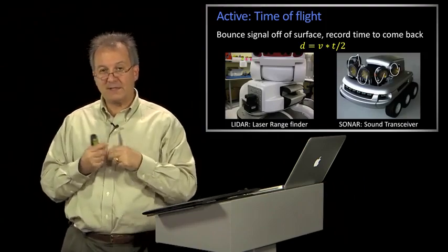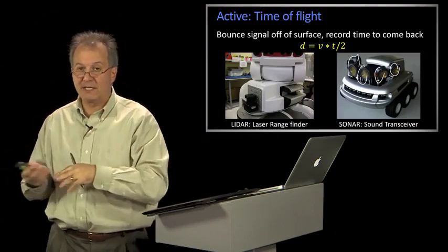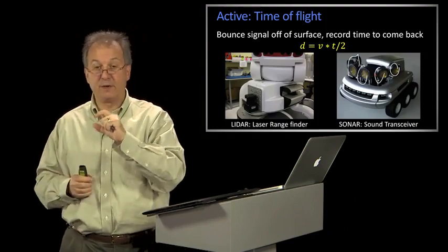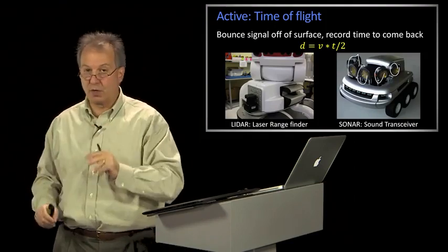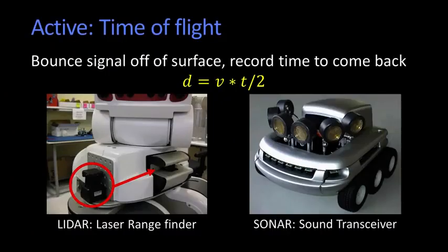One of the interesting effects of that is because they made so many of those cameras, it made those sonar things very cheap. So people started putting them all over robots and things like that and using sonar to detect depth. Much more sophisticated is what's called LiDAR, or a laser rangefinder. There's two of them here. One is on the side over here. One is stuck in here. These are on a PR2 robot.